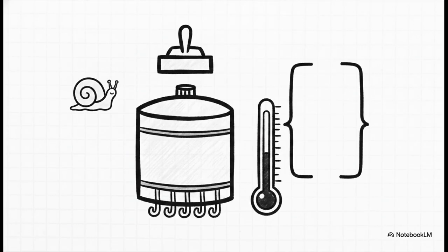Actually, the answer is a definitive no. Putting a full modulating loop on a simple tank heater would be totally wasted money. The tolerance here is incredibly wide, and a giant tank of water is a very slow-moving process. That wide tolerance perfectly suits simple, cheap on-off control.